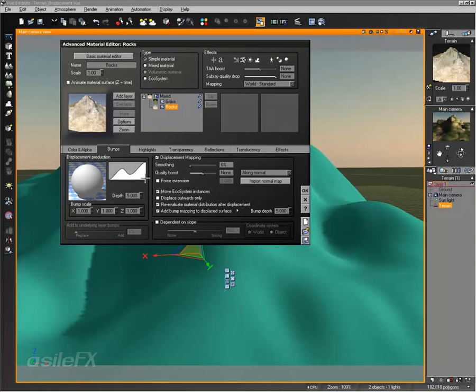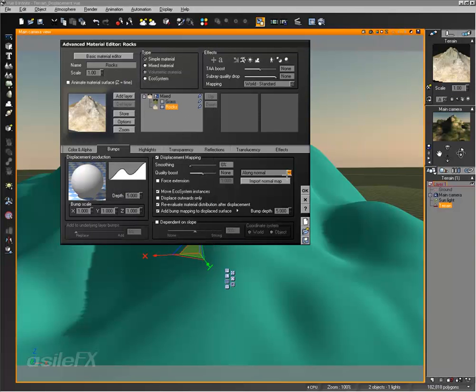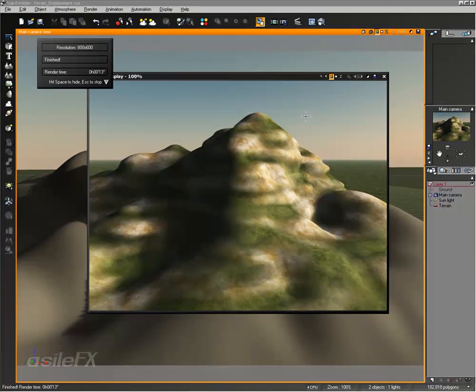since some changes have been made to the way filters will clip. If I was to drag out and take this endpoint and really twist it around so that it's curving too much, and depending on what clamping mode you're using, it can produce some very interesting results. So the default mode is along normal. Let's go ahead and switch it over to horizontal only, which will just displace along the X and Y. So if your Z-axis is up, there will be no displacement.